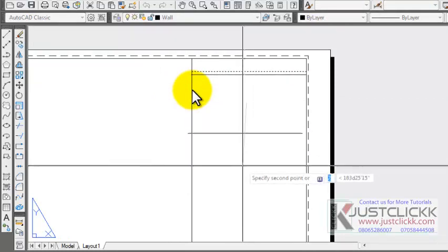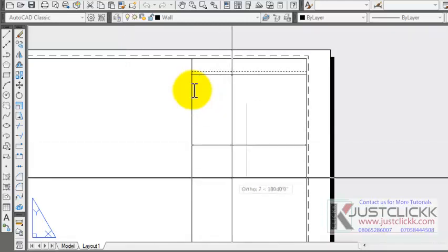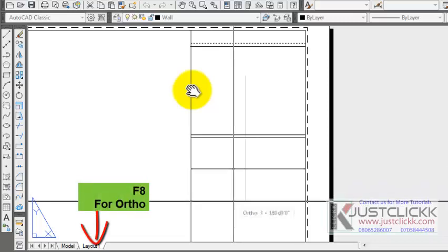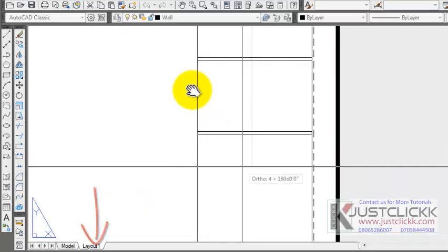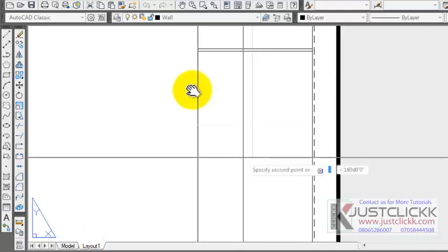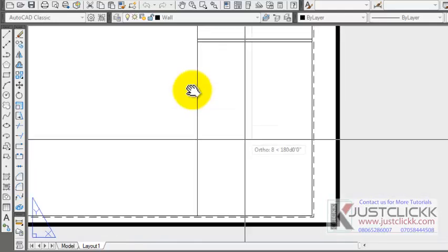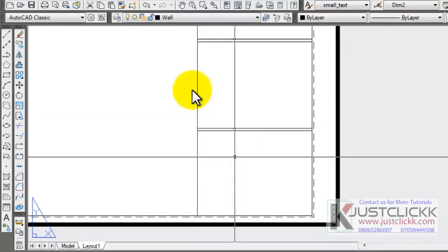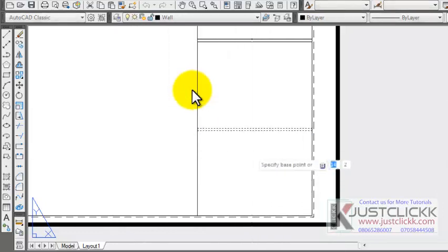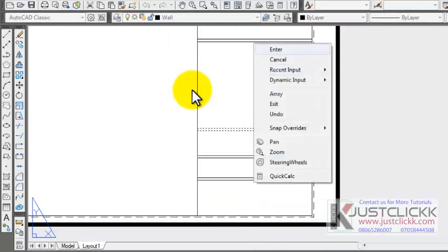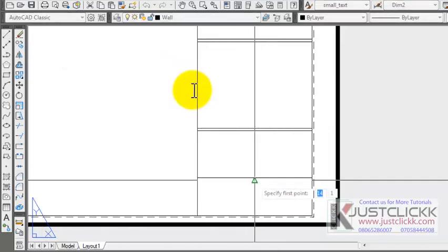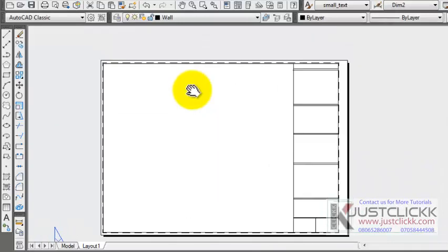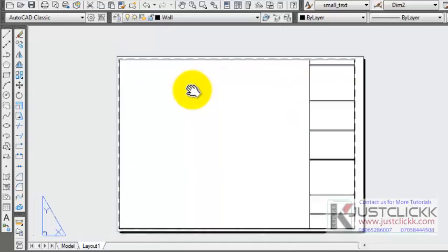Created a copy there. We can enable our auto. Auto will give us a great assistance. So let's continue to duplicate it in that manner, create partitions that will enable us describe our project. That's what is happening right there. Okay, like so. And I will copy this as well down here. Okay, and then I'll pick a line to partition this very section. Okay, so this is how you can prepare your title block.